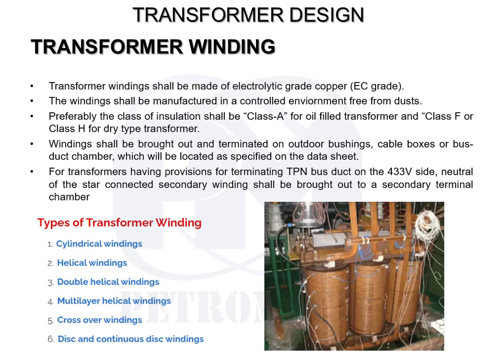Now the selection of the winding which suits your transformer is exclusively based on the voltage requirements. In LV we may use a specific winding which may not be compatible for HV winding for a particular voltage grade, whereas for a voltage greater than some particular value we may have to go for a specific winding, let's say disc winding.